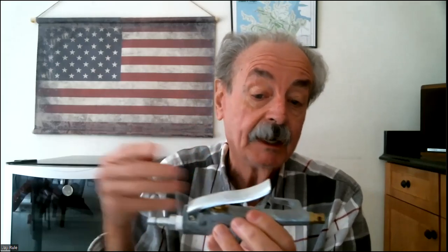So a supply of compressed air comes in here, okay? And of course the exit is here, and we simply press this open close valve down to get the air flowing. Now, let's see, I'm going to look on this. Yes, here it says right here on the wording of this nozzle, it says 150 PSI maximum inlet pressure. And so this is designed for a maximum of 150 PSI.